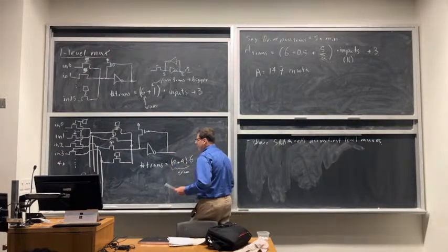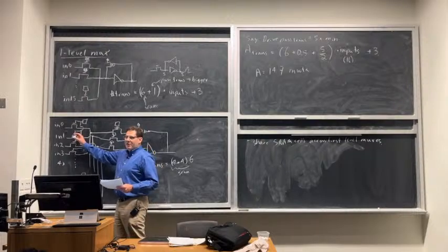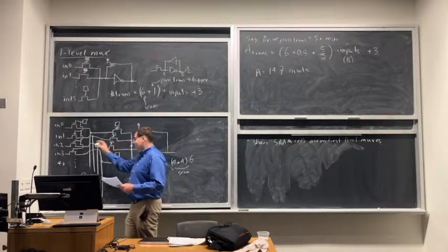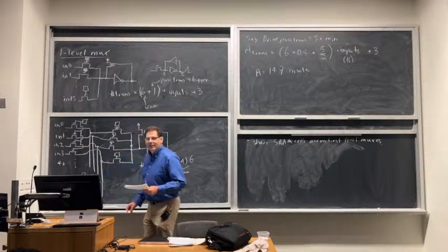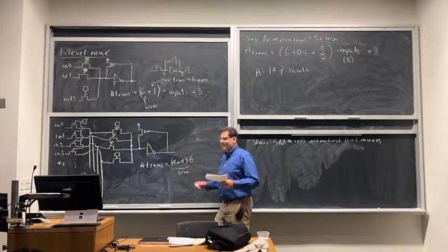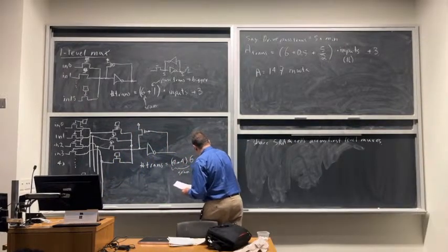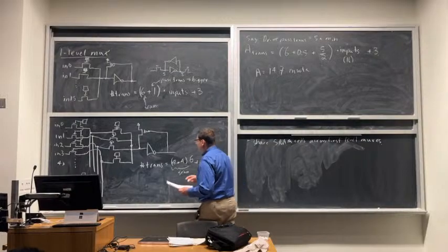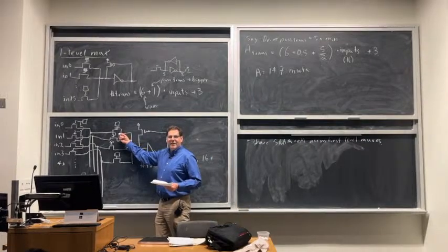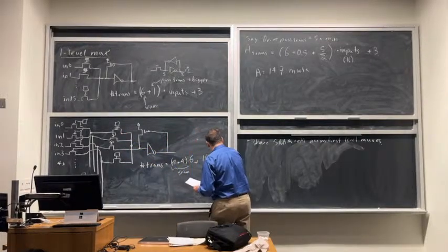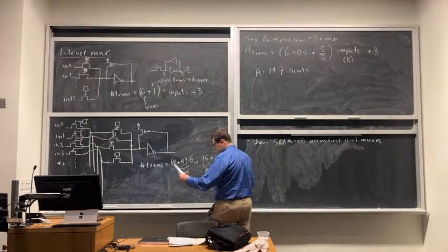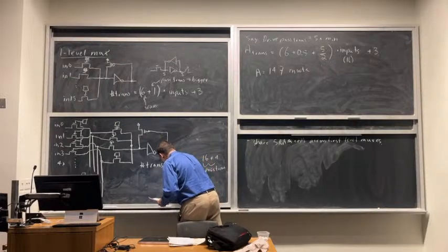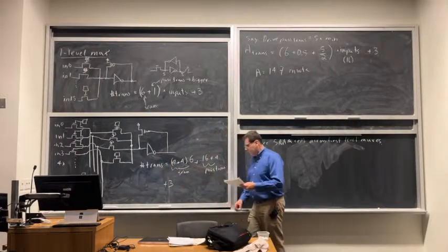Okay, then pass transistors. So you just add up how many in the first stage, how many in the second stage. First stage is actually always easy. So how many in the first stage for 16 inputs? It's just 16, right? So you need 1 per input in the first stage, plus 16, and the number in the second stage you can see right here, right? It's a 4-to-1 mux. So 16 plus 4. Okay, so that's pass transistors. And then we always have our usual output restoring circuitry, so 3 more.